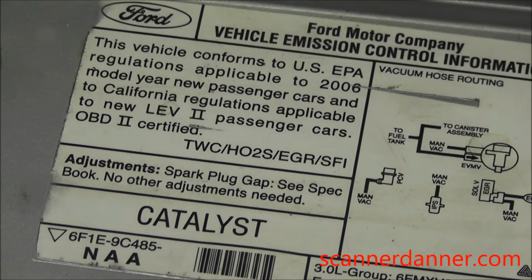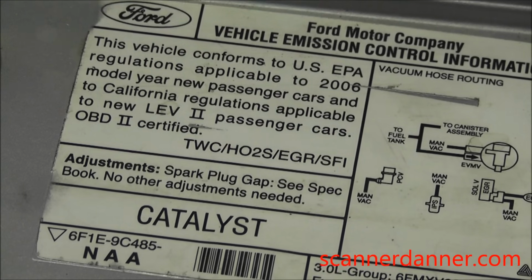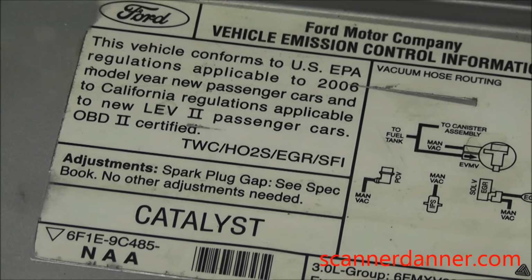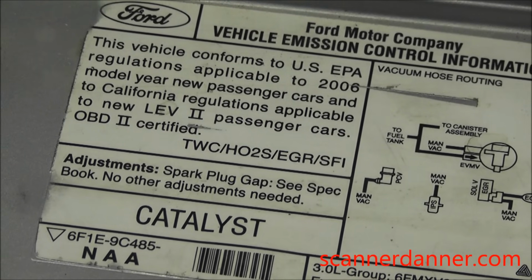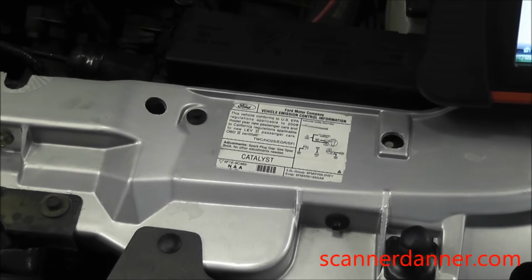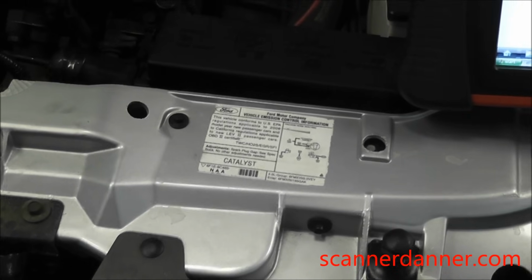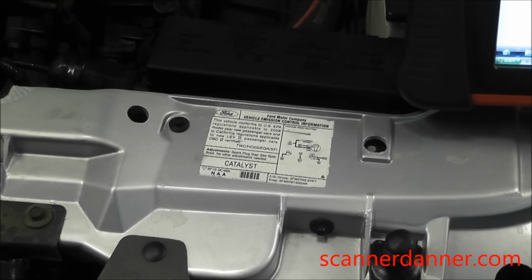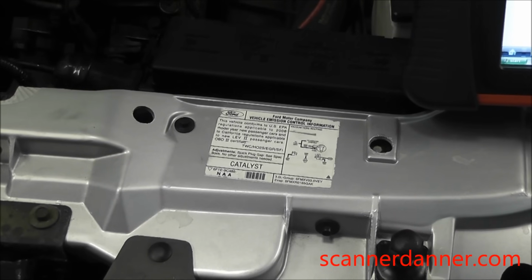All right, little discrepancy here, guys. One of the reasons we need to be careful about model years and where we're getting our information from. This car is from a body shop. This has a label on the front. It says it's a 2006, but the VIN tag, the 10th VIN number is a 7, so this is actually a 2007. And I had it entered right on the scan tool. I misquoted this video at the beginning. This is a 2007. Go by the VIN tag behind the windshield when in doubt.